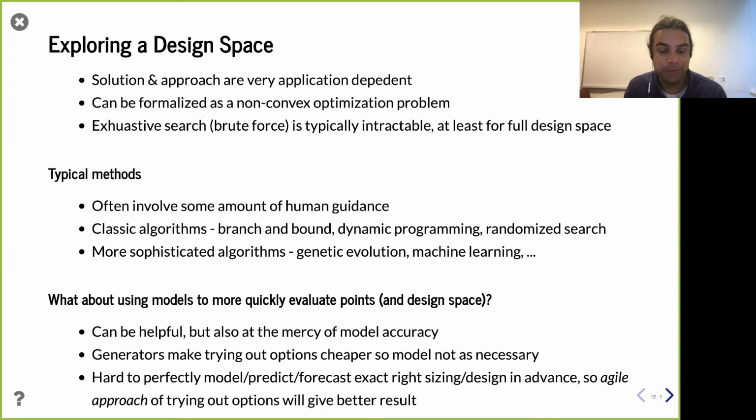In a waterfall approach, you do DSE first with simulation and models, and then you start building your actual chip, or start designing each block, and then each block has to meet some performance criteria. But it's open loop, right? You have no idea if those performance points are achievable or if they're going to fit in the area budgets. It's all based on how good you can model. If you can model really, really well, both in how well you can build things and how well they're going to perform, then yes, perhaps you could do waterfall with DSE at the beginning. But in practice, it's really hard to get some of these things right. A company like AMD, who has billions of dollars at stake, needed to get it right, and they didn't. So it's important to get this sorted out.